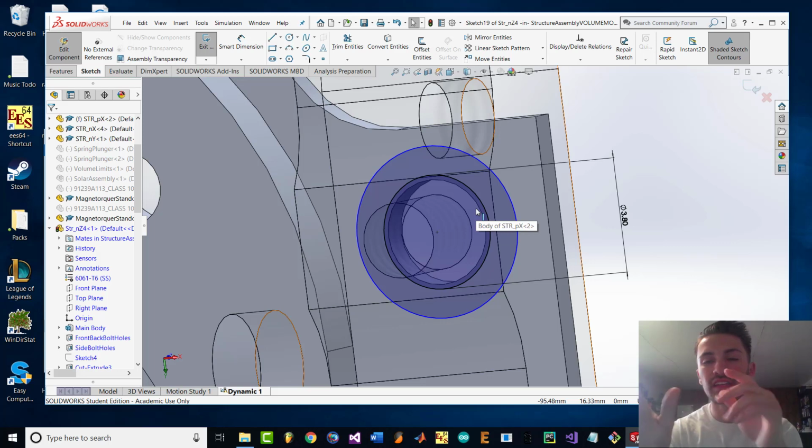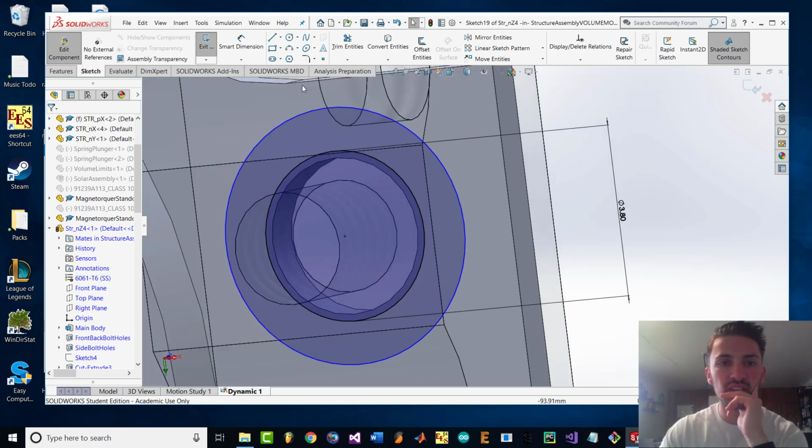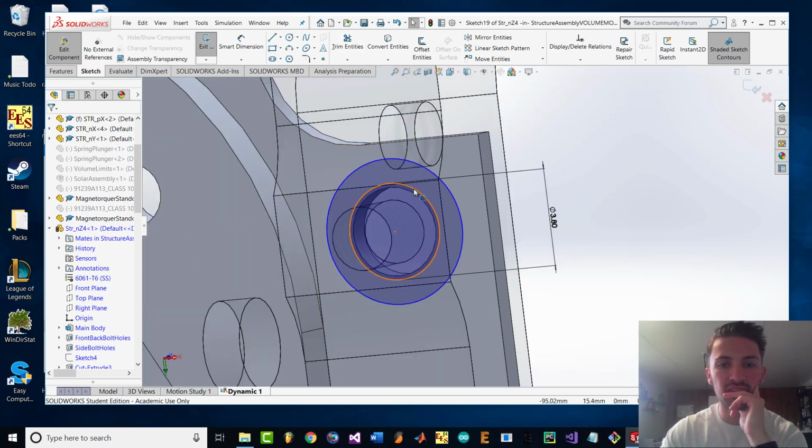So we'll create 2 circles, make the smallest one 3 millimeters. Actually, I stand corrected. Even though the bolt is 3 millimeters wide at the threads and about 5.5 millimeters at the head, because of tolerance we're making the holes 3.5 millimeters, so we have some slop so we can line things up. We're going to want to make the inner circle the size of this hole.